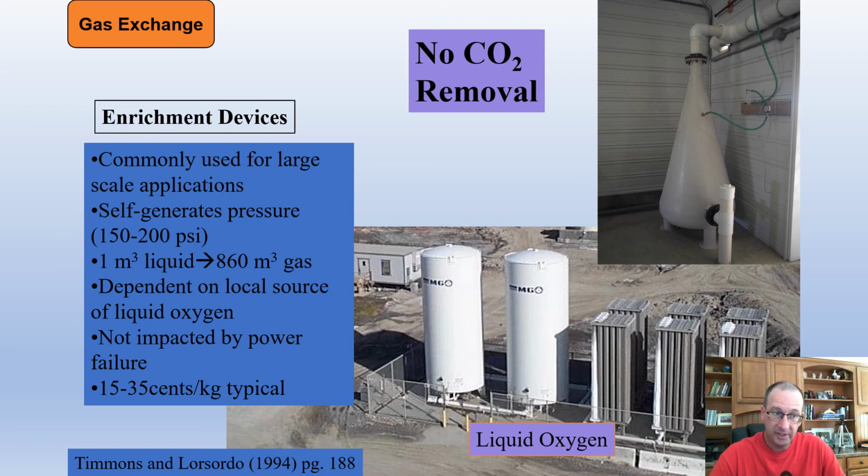They actually stay off until the power goes out. And once the power goes out, the valve that is normally being held closed by an electrical current opens up and lets the oxygen gas flow out. So you get automatic oxygen going to your fish instead of just a little bit of air. And if we're putting pure oxygen into the system, that brings the O2 level of the water up significantly in a very, very short amount of time.